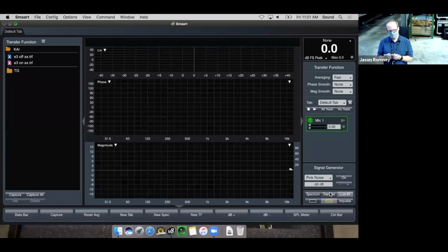One of the best ways to make a microphone have a flat frequency response is to make it omnidirectional. One of the reasons the SM58, for example, has a not flat frequency response is that the things they have to do to the mic to make it cardioid, to make it really sensitive in this direction but not sensitive in the other direction, affect the frequency response.